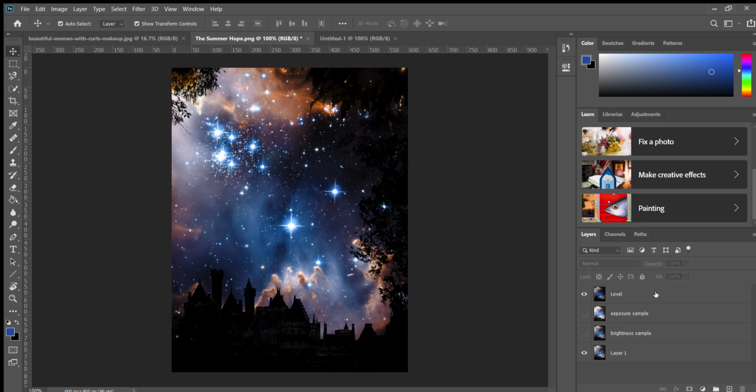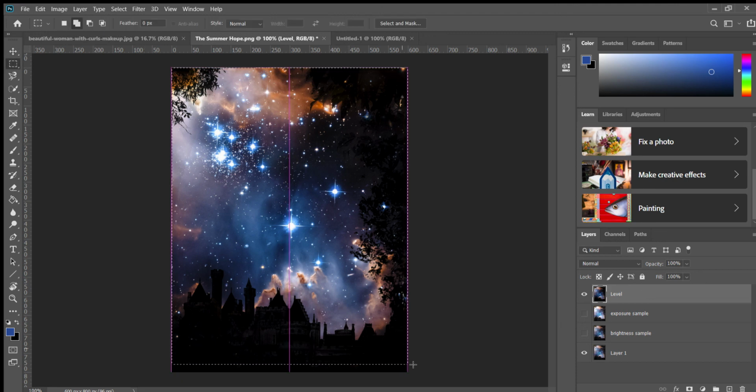Now if you're already satisfied with your image, assuming that we want our background image similar to this level, you can use the marquee tool to take this image. Just draw that big square, taking the whole image, and then press Control C, or go to Edit, Copy. Go back to your main artboard, which is this untitled here.